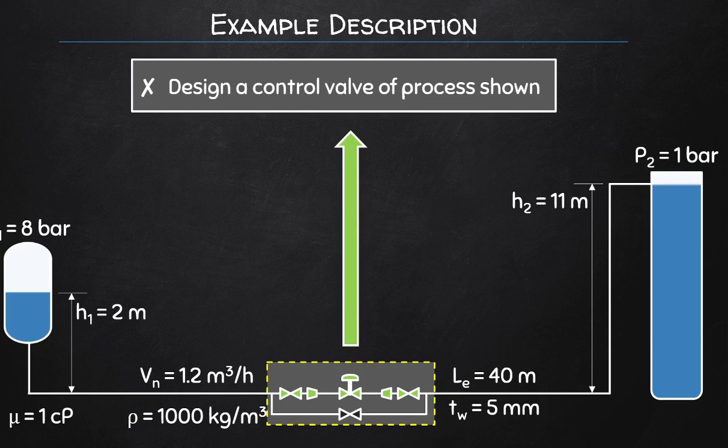Perhaps we calculated a required wall thickness. We found that the corrosion factor was 3 millimeter, and the rest of the requirements to maintain the integrity of the pipeline was equated to maybe 0.7 millimeter, which was rounded off to 1 millimeter.